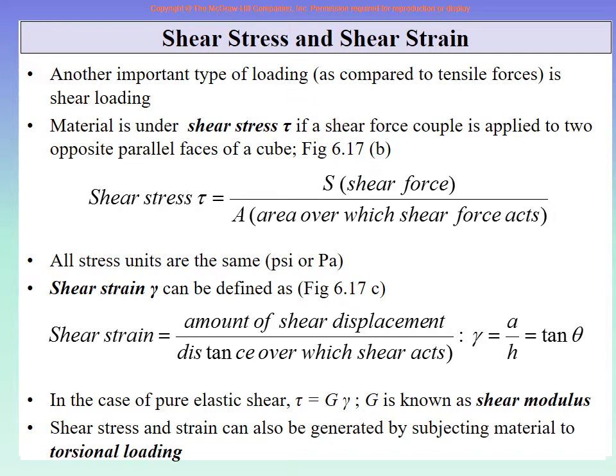But just remember that normal force means if there is an area, the force is at 90 degrees to the area. If the force is parallel to the area, then it is a shear force that you know. So that is what we will show you in the figure. But the definition of stress is the same. Definition is force upon area. So now it is shear stress. So it is shear force upon average area. So the area on which it acts and the force, which is the shear force this time.